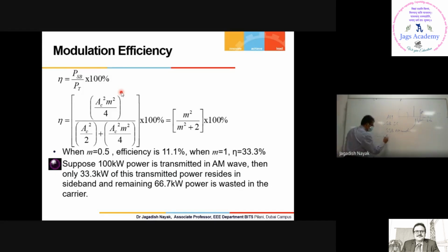Okay, see, this is multiplier, we call it the modulator. Okay, now actually mathematically we are multiplying this. Okay, and this will be your message signal m of t is equal to Am cos omega m t, right? And here comes the carrier. The carrier will be your Ac cos omega c t. Just multiply this. Right. When you multiply this, you will get a double sideband suppressed carrier wave.